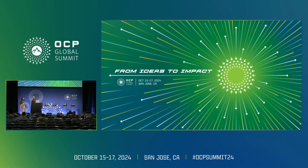Actually, you have touched a very important point. Traditionally, that's why the DFT techniques evolved. The way ATE technologies have evolved and our silicon implementation technology has evolved, there's a big gap. Companies like Teradyne and Advantest are the main test companies. Finally, it is the pin electronics; they cannot be inside, right? That's the whole idea of built-in self-test. Outside pin electronics, which is required to go to the probes, is not going to sustainably keep pace with the process.